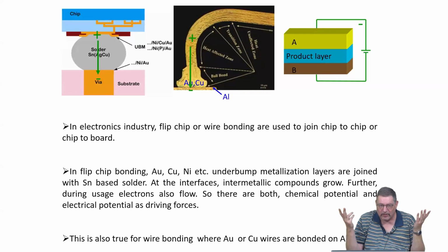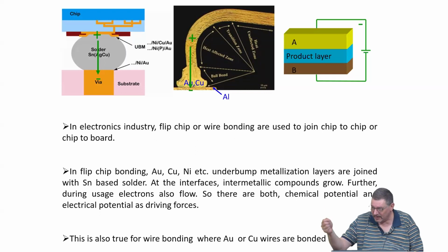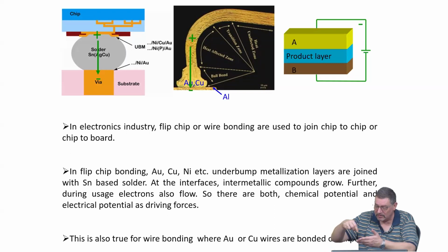So diffusion bonding, the term is very well known. It's also very important to do quick bonding on a chip, for example, of gold wires. It's typically done not by soldering or anything like that, but by this wire bonding. So you tip the wire and the current flows as soon as the interaction distance is small enough, and then automatically it's heated up in the right position and it will do the bonding.